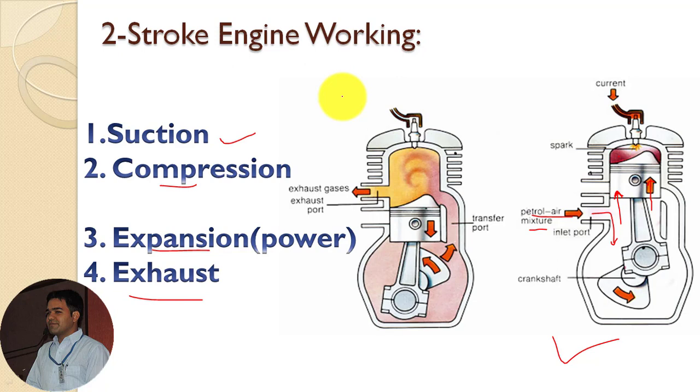So during this movement, while the piston is traveling from bottom dead center to top dead center, that means during the first stroke, you can assume that the suction process and simultaneously the compression process occur. So we can say that suction and compression occur during the first stroke.